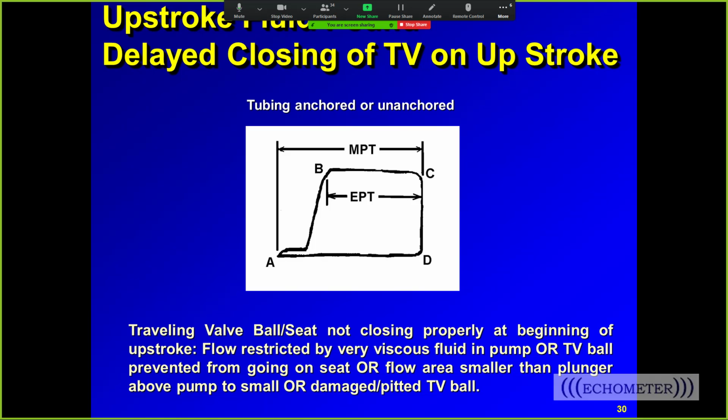In many wells when you have the hole below the liquid level, the liquid level in the casing and tubing aren't exactly the same, because there's different liquid in the tubing and casing, and the only place the pressure is equal is at the hole, at the intake. Anyway, the liquid levels won't be the same height.